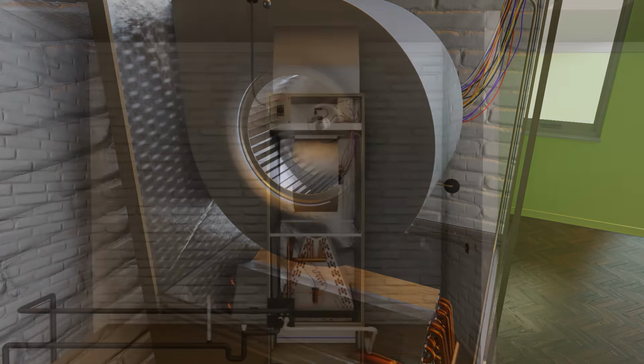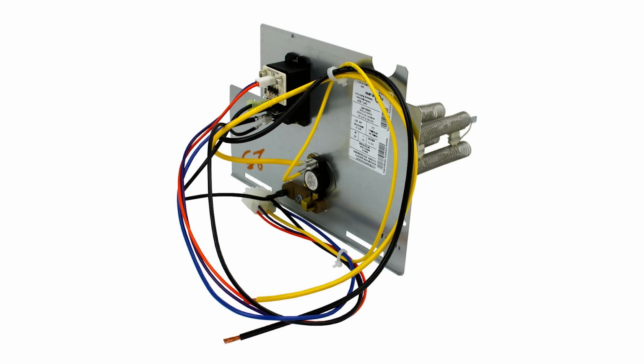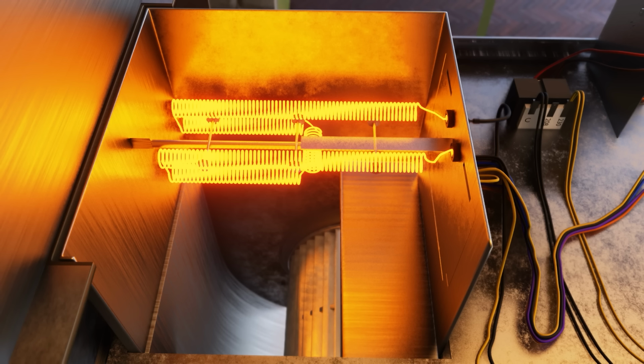Because this is a heat pump, I also want to introduce you to the heat strips or the auxiliary heat. Heat strips are just there to provide some additional heat in cases where the heat pump isn't keeping up with the load or when the heat pump is in defrost. When the system goes into defrost, the defrost board energizes the heat strips on the inside, as well as shuts off the condenser fan on the outside and shifts the unit back into cool mode to defrost any ice that may have built up on that outside coil.